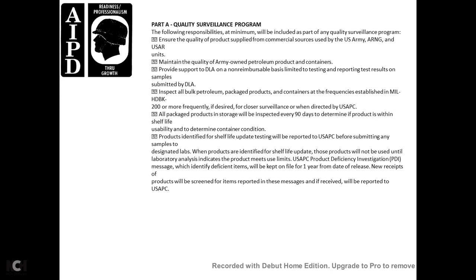Provide support to the Defense Logistics Agency, on a non-reimbursable basis, for testing, and report test results on samples submitted by the Defense Logistics Agency. Inspect bulk petroleum tank trucks and containers with the frequency established in Military Handbook 200, and before they are cleared for servicing with the U.S. APC. Packaged products in storage will be inspected every 90 days to determine if they are within shelf life and to determine the usability and container condition.